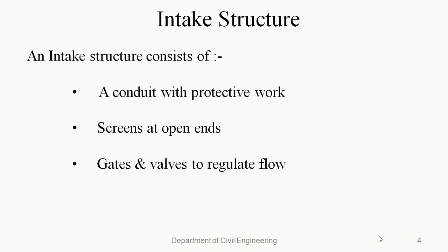So, to perform tasks such as collection and conveyance of water, an intake structure consists of the following points. Number 1, a conduit with protective work. Number 2, filter screens at open ends. Number 3, gates and valves to regulate the flow of water.